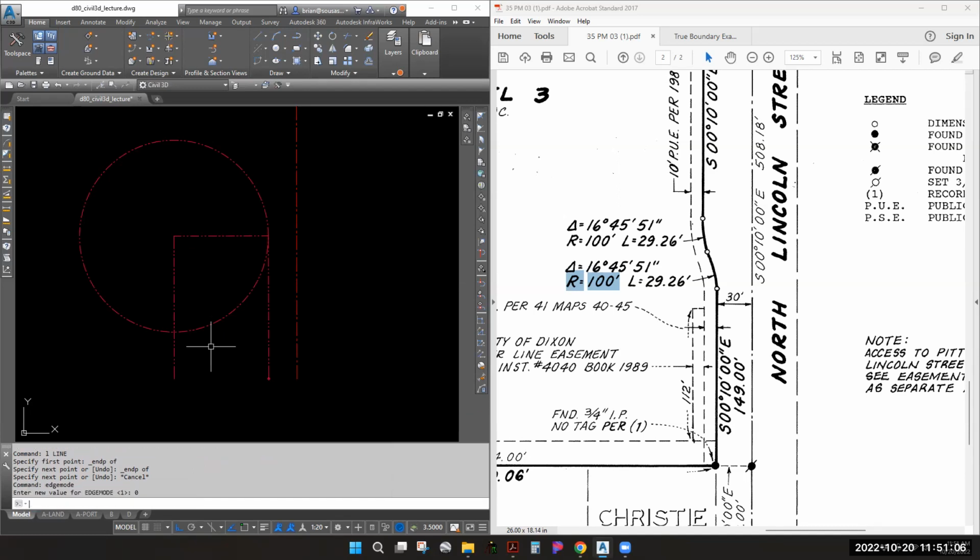By default, when you load AutoCAD or Civil3D, edge mode is set to 0. 0 meaning off, okay? 0 always means off, 1 always means on. When you set edge mode to on or off, it's always going to stay on or off until you change that command. So whether you get out of CAD, you turn your computer off, you turn your computer on, edge mode is still set as you set it, okay?